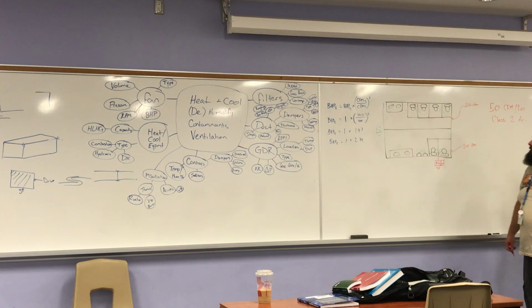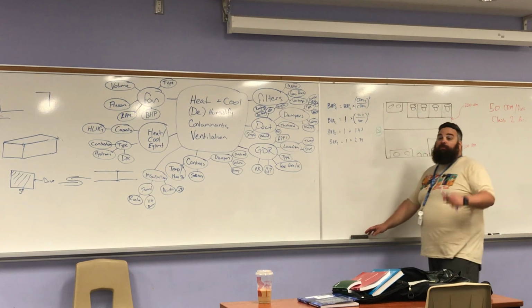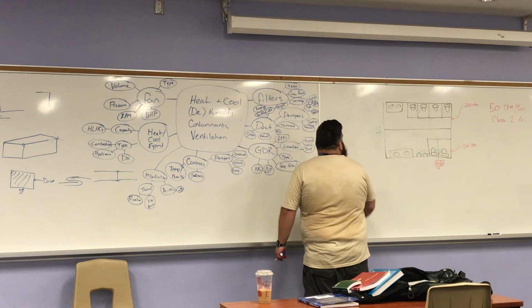Over 400. At least 400. Both washrooms, both women's and men's. Right, but we're keeping it at the 100 CFM, right? We said we could do the 580. So how many CFM does EF1 need to be?